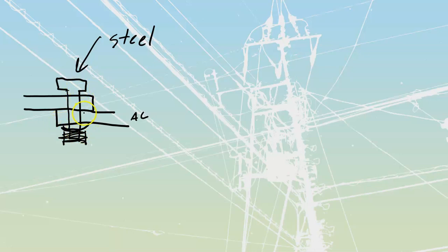That means that now as these bus bars expand and contract due to heat and current that we're flowing through there, there's always going to be pressure that's going to be applied by this conical spring washer. Sometimes we'll use split spring washers as well, but it's far more common for us to use those conical ones. They give you an example for a recommended torque, for 1/4 inch bolts, and they show you how to do it inside of the module on page 31.